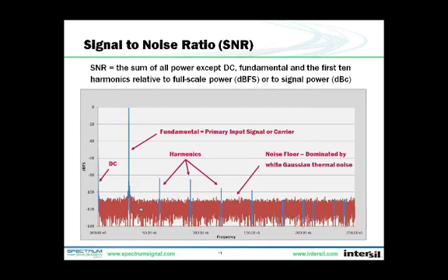So ADCs, when we test them, are typically characterized with a single frequency sine wave input, and that would generate this large blue tone right here. We would call it the fundamental, or a tone, a signal. This sine wave test is the most difficult case because if instead you use a wideband signal with multiple frequencies, like a spread spectrum signal, that range of frequencies will tend to randomize any linearity errors in the ADC, and you'll get better results. It's also easier, or maybe we would say more consistent, to process a fast Fourier transform or an FFT result with a single sine wave input.